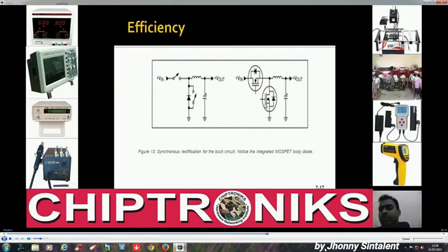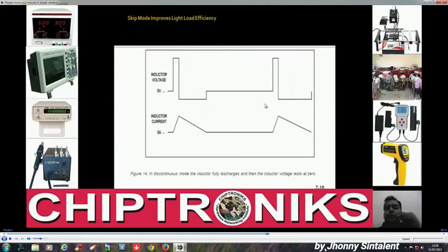In a notebook motherboard, a synchronous switching regulator is used, and this is skip mode. Skip modes are present in some regulator ICs. What exactly is skip mode? If our output voltage is fixed for a certain time, with no disturbance in the output voltage, then the gate drive pulse can be switched off for some time. We can skip some cycles, right?